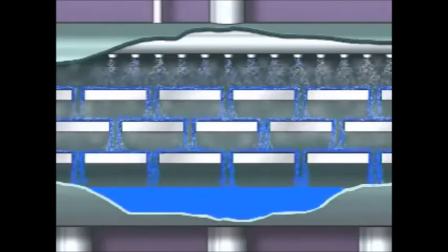The heated and deaerated condensate that collects in the bottom of the heater is actually a mixture of condensate and drips from the heater. From the deaerator, the liquid will go to the hot surge tank for storage. From there, it will go on through the condensate and feed water system to the boiler. Air and non-condensable gases that are removed from the condensate flow out of the deaerator through a vent.